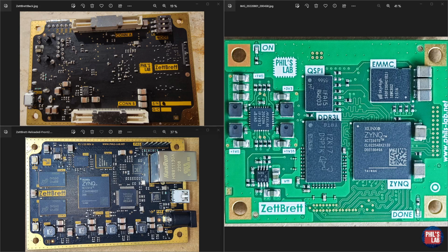The boards you're seeing here are fairly high-speed digital boards, and oftentimes when we get into these high-speed digital areas, we need to think of termination, as we'll see, to minimize reflections, improve signal integrity, and EMI performance. I'll show you how I did this on some of these boards.